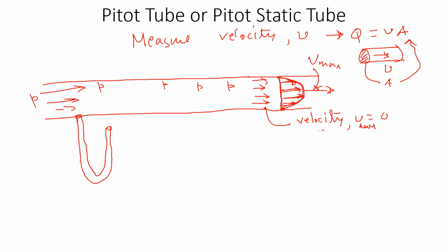So when it pressurizes the manometer fluid, because you have high pressure here and let's say the atmosphere has less pressure, it will create a pressure difference. Now, because there is no velocity head at the wall, because the velocity is zero, this pressure difference is called static pressure, PS. So this pressure difference is the static pressure difference or height HS.